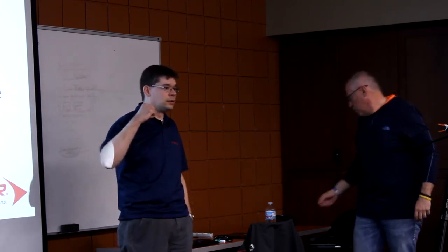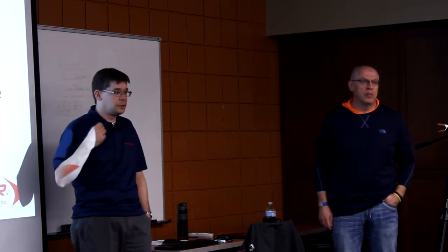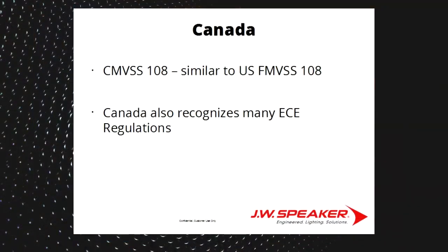Yeah, and that's a good point. So when we have our homologation agency here and we're doing testing, we do a photometry test, but then we have to do multiple other tests with photometry afterwards to do all the testing that's required. So usually if we do a headlamp, we have to test 2 samples. It's 2 days of testing here that we have to spend to go through and do all the tests that are required. Canada, Dragan had mentioned this, CMVSS 108.